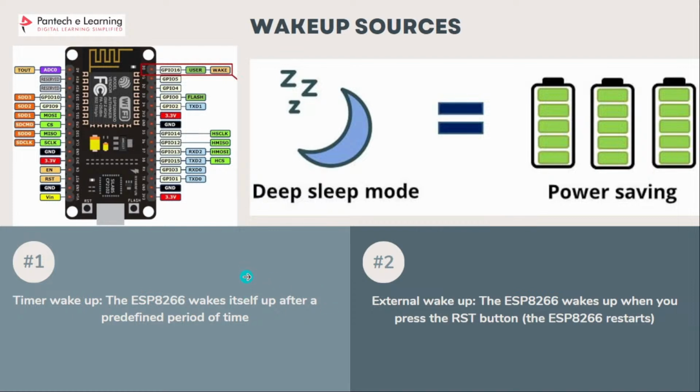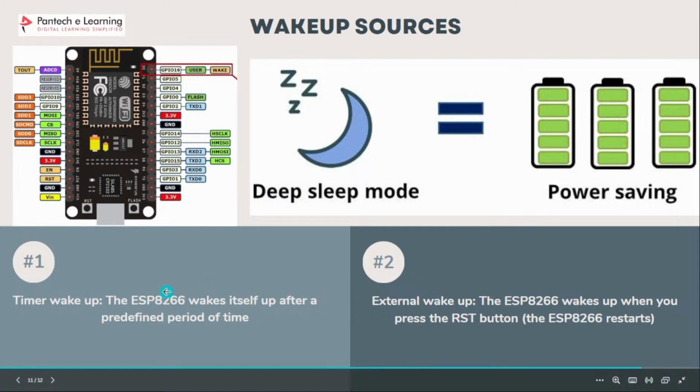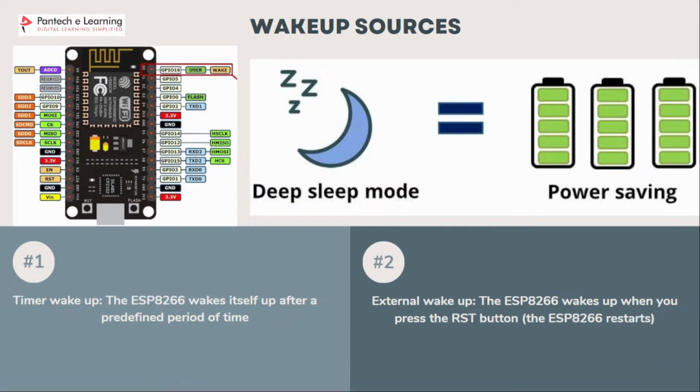And then coming to wake up sources. After putting the ESP8266 in deep sleep mode, how can we wake it up? There are different ways to wake it up. One is timer wake up, another one is external wake up. In timer wake up, the ESP8266 wakes itself up after a predefined period of time. And in external wake up, the ESP8266 wakes up when you press the reset button, so the ESP8266 restarts.